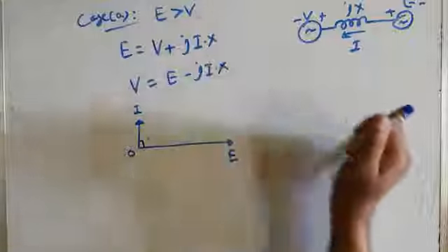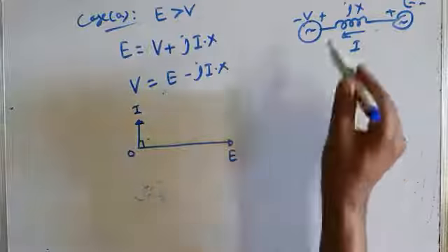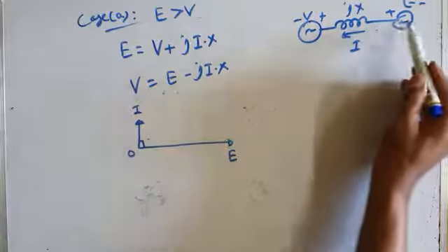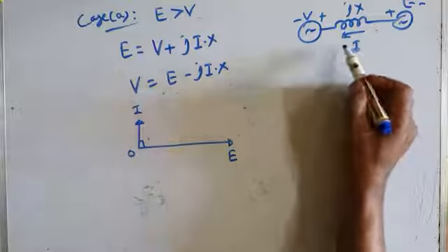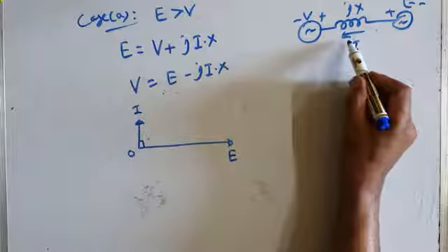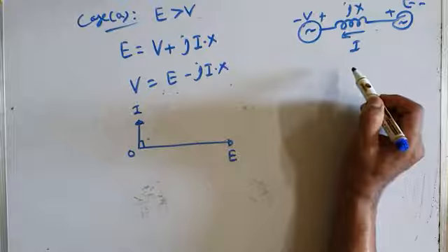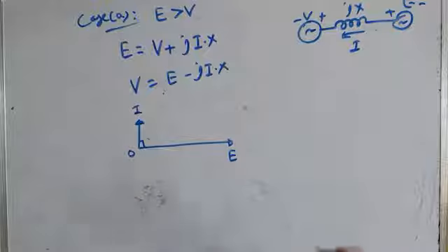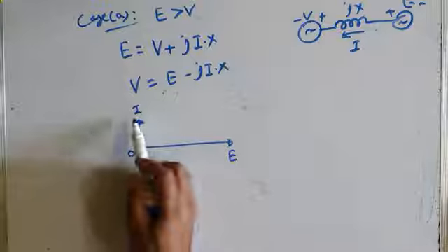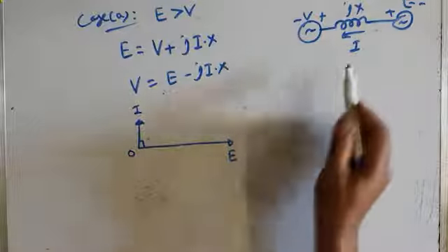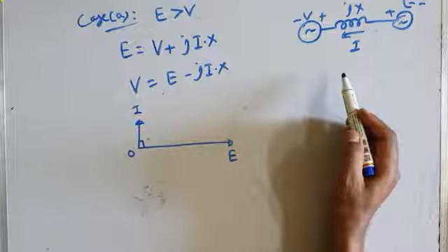Because when the machine is in overexcitation state, when the machine is overexcited, the system sees the machine as a capacitor. The machine draws this leading power factor current I. In other words, it generates the reactive power and injects that reactive power into the AC bus. So the current I is leading E by 90 degrees because this current is at leading power factor.